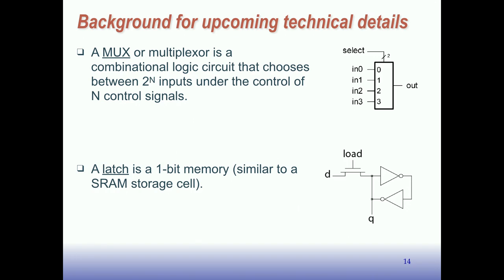I'm also going to talk about latches. Now, we've talked about flip-flops. There's a similar idea called a latch. And as we'll see later, flip-flops are actually built out of latches. But this is a more primitive element. A latch is similar to a storage cell, an SRAM storage cell. It's a place to store a bit.